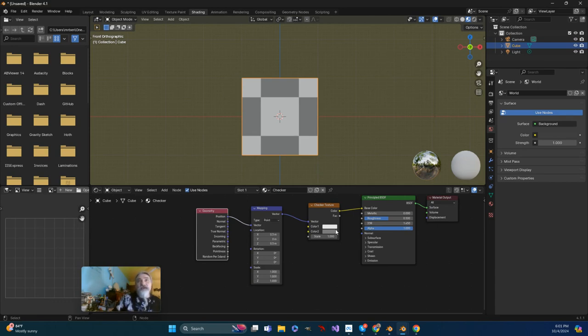Likewise, I can scale now. Instead of scaling here where it's just the entire thing, I can scale just on one axis. So if I want these to be narrower, maybe I want X to be scaled at 5. Maybe I want Z to be taller yet, and maybe I want Z to be 0.75. That's all something I can do.